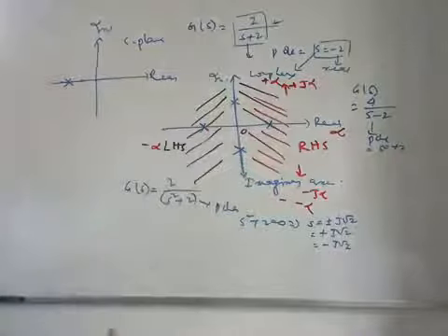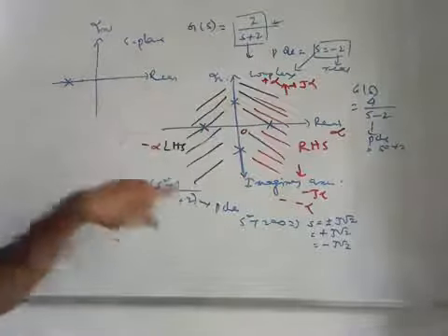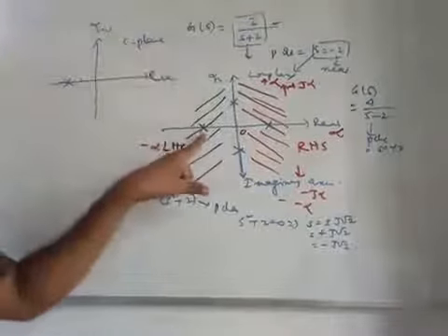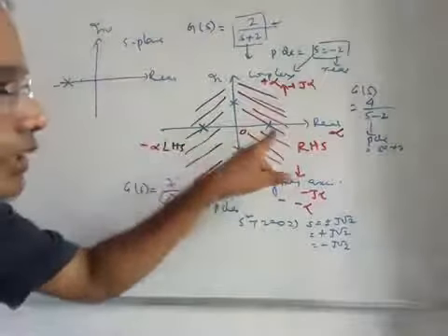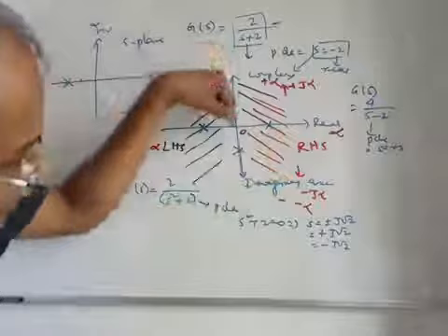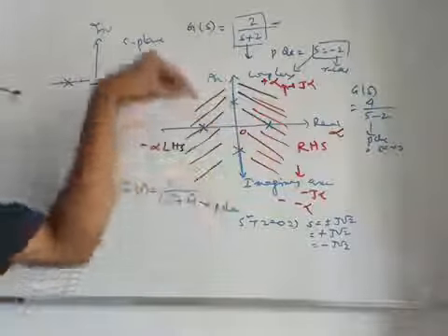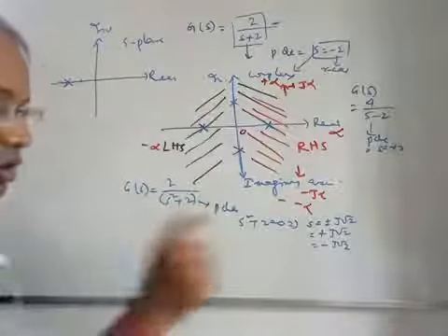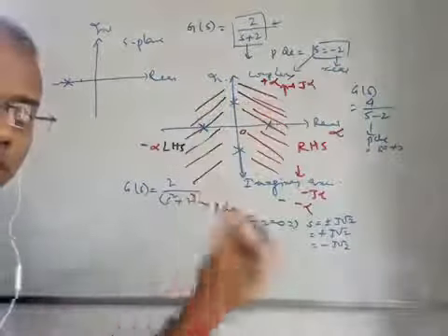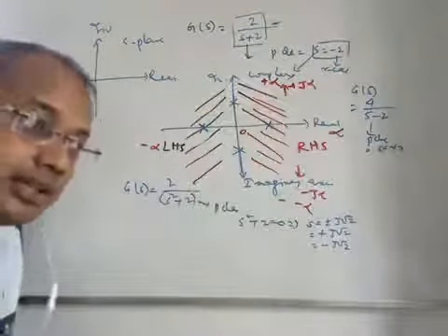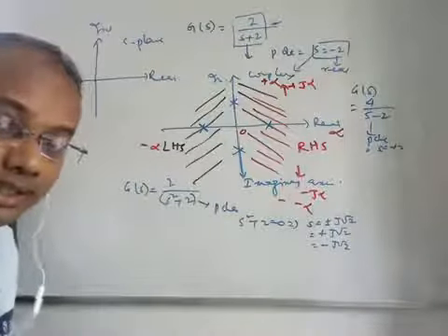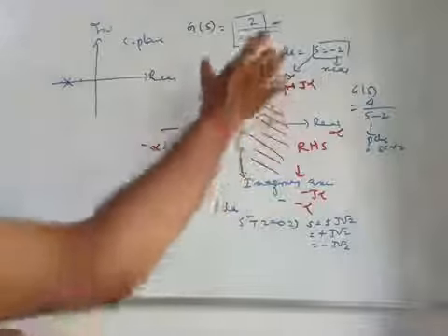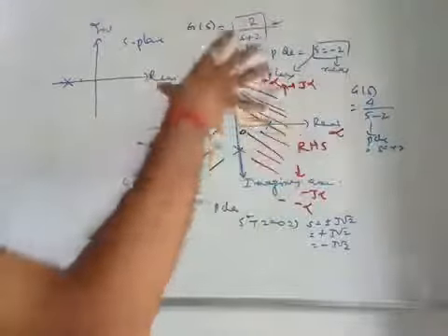So we have considered the three examples, where you can see the pole may be on the left hand side of the S-plane, on the right hand side of the S-plane, or on the imaginary axis, right? So these are the pole locations or the roots. Basically these are known as the poles or roots which characterize the system, because you know the characteristic equation, we have already discussed. Now you see these are actually the locations of the poles.